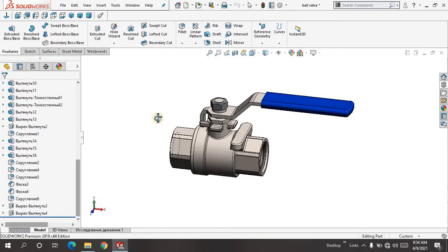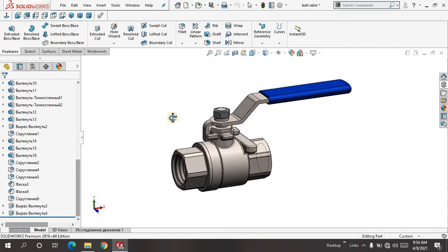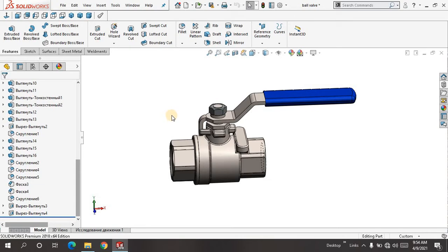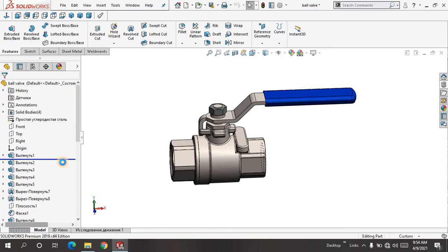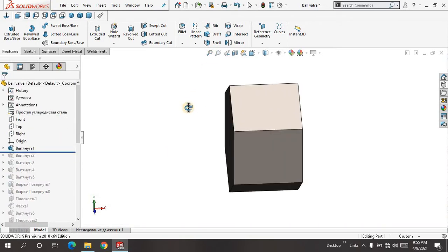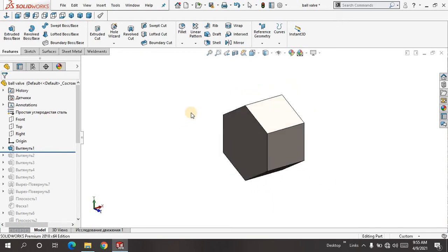So this is really very helpful for the beginners, and also for the experts in SolidWorks. First of all, we will see from where we have started this ball valve and where we have ended this. So let me suppress the other features. Just come downward and hold your mouse on the green line, and let me drag it up like this, up to here.